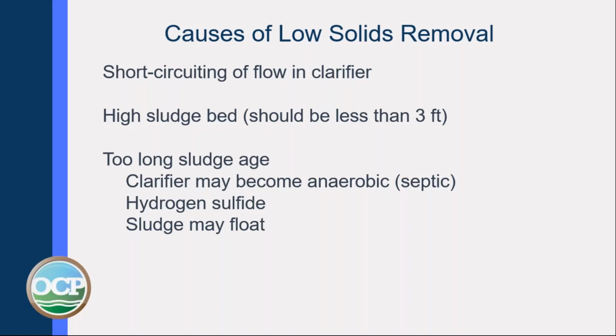If you age the sludge too long by not pumping it, the clarifier may become anaerobic. It will produce hydrogen sulfide and other gases that will cause the sludge to float, and it can float over your weirs and go into your secondary treatment system.